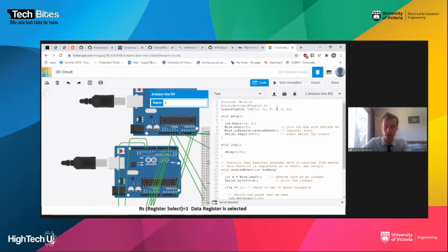If we had wanted to do 8-bit mode, we would have included the other ones. We're then saying that we're going to start the LCD display, turn it on, and we're using 16 columns and 2 rows. This says that we're starting this device with the wire library, and we're using this as address 4. And then it's waiting to receive an event.